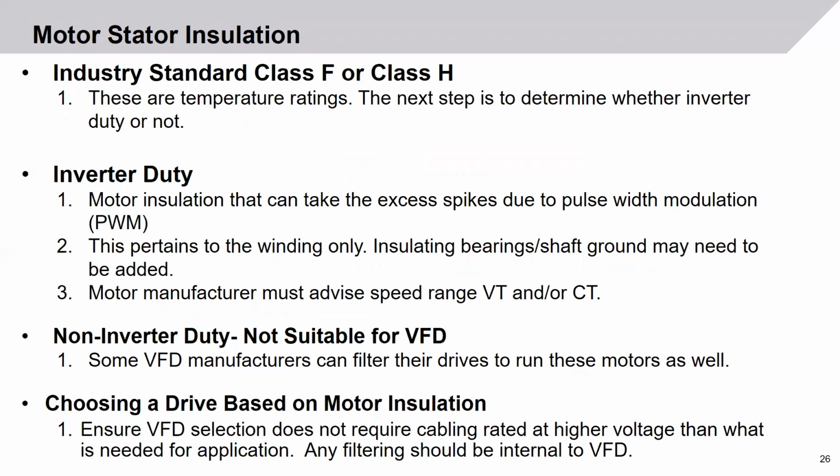The next step is to determine whether they are inverter duty or not. If the motor insulation is considered inverter duty, that means that the motor insulation can take the excess spikes due to pulse width modulation, otherwise known as PWM. However, inverter duty rating pertains to the winding only. Insulated bearings and or shaft grounding may still need to be added.